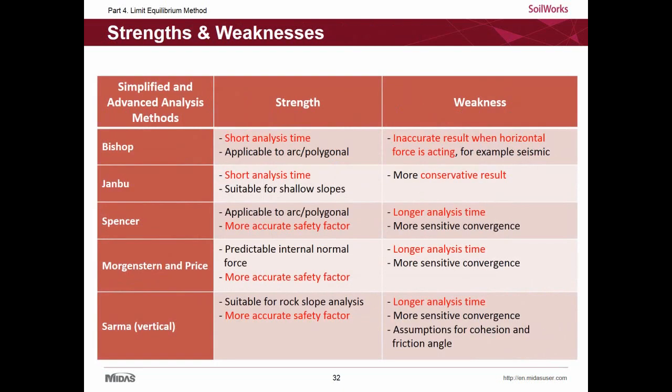Let's discuss the strengths and weaknesses of the different LEM methods, based on which engineers can make a choice for the analysis method. So Bishop and Janbu are simplified methods, like I said earlier. The time taken in these cases is less, but the results are inaccurate when it comes to horizontal loads.